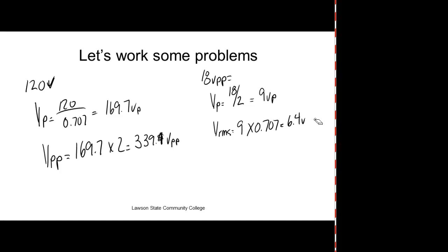Now we're talking about AC. And this is important, but the DC average of a cycle is 0. And this is why when you put your meter on DC and you look at an AC signal, it's going to measure 0, if it's a sine wave. If it's non-sinusoidal, which means if your positive is greater than your negative, then your meter will show you some positive value, but it's not going to be right. You understand?